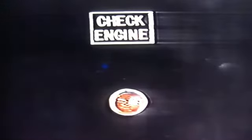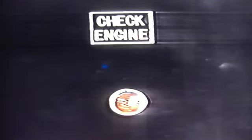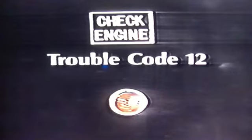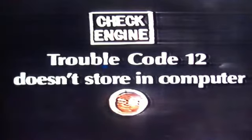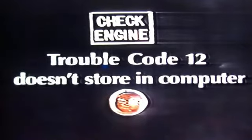following sequence: 1 flash, pause, then 2 flashes. It will flash this sequence of 1, 2, a total of 3 times, and it's called a trouble code 12. It tells you the ECM has diagnostic ability. A trouble code 12 also indicates that the computer is not receiving a distributor reference pulse, or more simply, any RPM information. But this is only logical since the engine is not operating. Most of all, remember that trouble code 12 is the only code that doesn't store in the computer. It goes away when the engine is started.